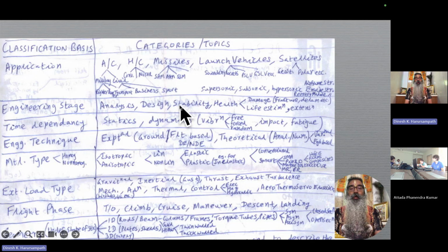There's also the analysis of the stability of the vehicle as a whole, stability and control, which involves the stability in the various dimensions in which it is there, and also the various rotations that are involved, like the pitch, roll, and yaw. So the roll and the yaw are coupled with each other and with the sideway motion, whereas the pitch and the vertical and the horizontal motions are coupled with each other. So there is a stability associated with that, and how the loads vary will have an implication as far as the structural analysis is concerned as well.